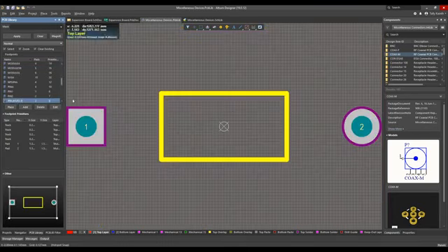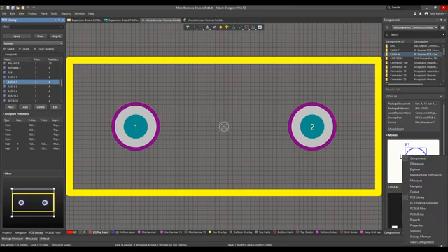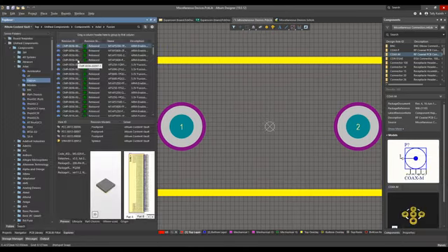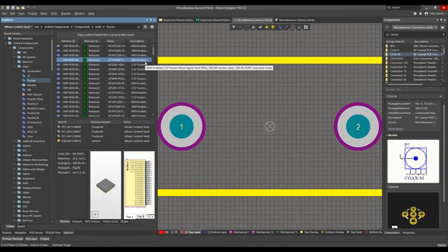In addition to these local libraries, there is an online resource for components called the Altium Content Vault, which can be accessed through the Explorer panel. This is a large collection of existing parts with both schematic symbols and their associated footprints. This is where we will get the bulk of our components for this design.